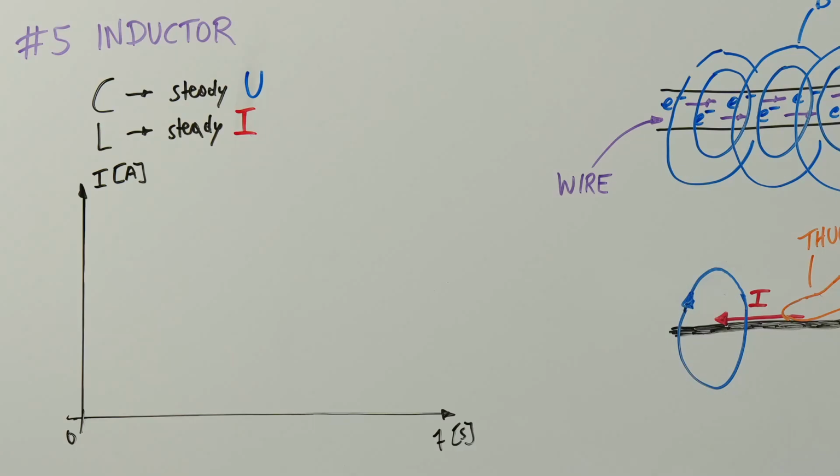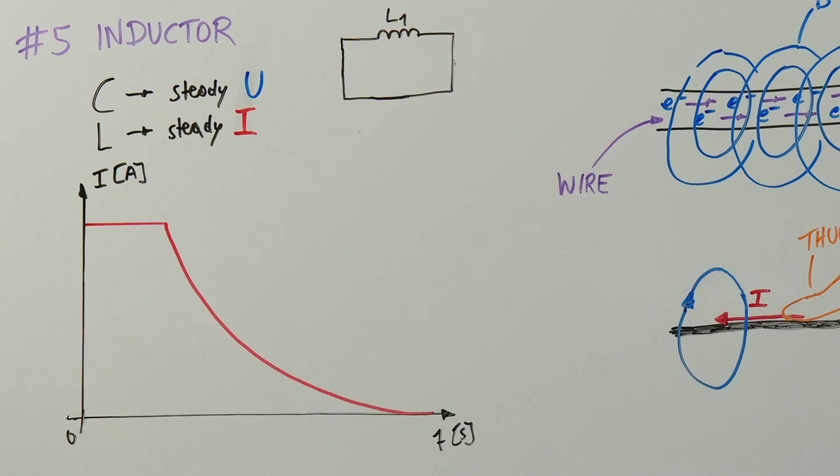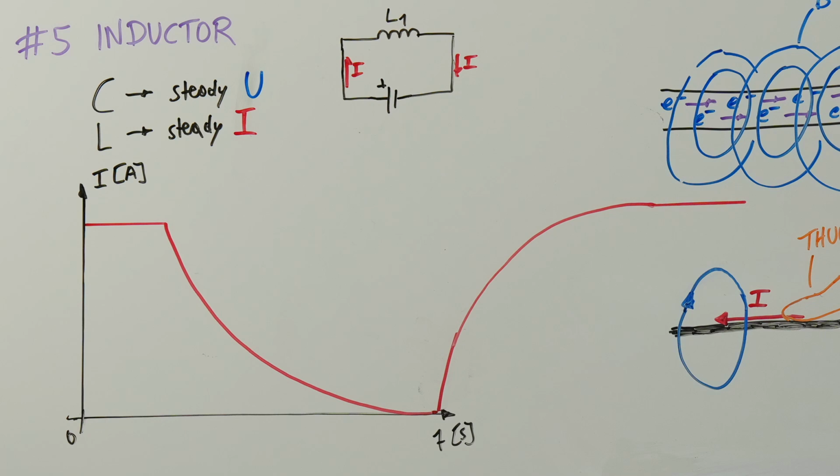A magnetic field always wants to remain steady and stores energy. If we turn off the voltage source, the magnetic field also wants to maintain its current state and induces a current so it can continue to flow for a while. If we turn on the voltage source so current can flow through a wire, the magnetic field induces a current and voltage in the opposite direction until the magnetic field is built up. Consequently, an inductor creates a lag in the current.